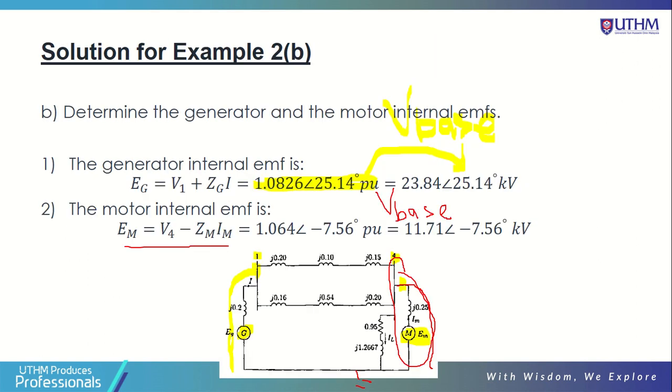Okay, I think that's all for today on how to use the per unit system to analyze the power system. From the per unit value, you can apply any circuit law, Kirchhoff voltage law, Kirchhoff current law, maybe divider rules and so on, to analyze your circuit. After you get your final answer in per unit, you can transfer to the actual or real value by multiplying with the base. If you calculate the voltage, you multiply the per unit value of the voltage by V base.